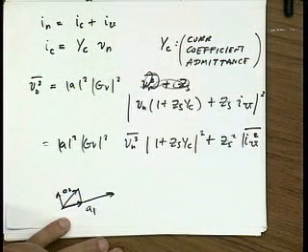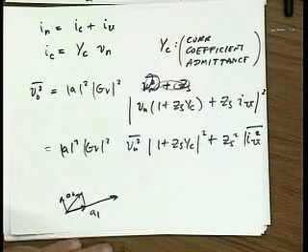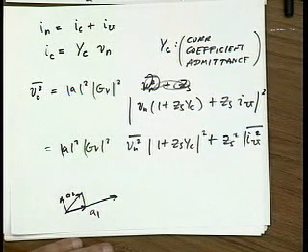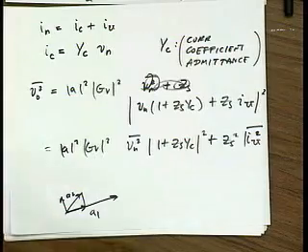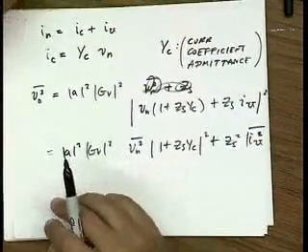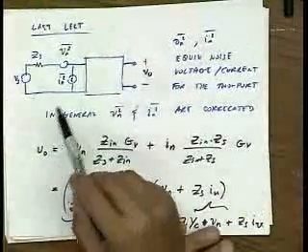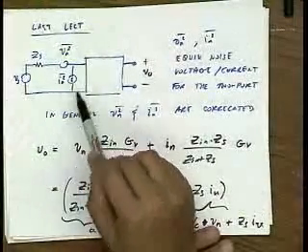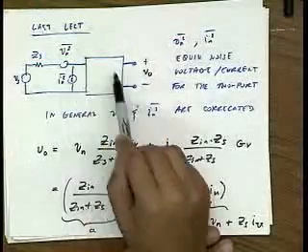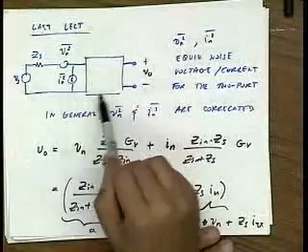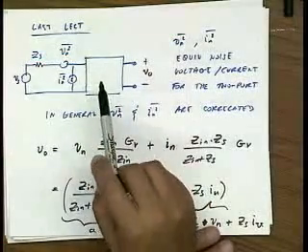So what is physically In composed of? Shot noise, which is totally uncorrelated with thermal noise, plus thermal noise. Okay. And we're not talking about any specific kind of noise here. So we're talking about a general two-port, right? So if I come back to my general two-port, when I calculate the equivalent current noise, right, it's going to be a linear combination of all the noise sources in this box, right?